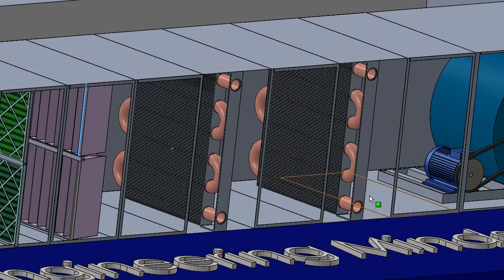It's good to have this connected so that the coldest water, and likewise the hottest water, is entering through the base of the coil and passing through. You'll get much greater efficiency out of this because it's going against the force of gravity, so it gives it a little bit extra time to give off its heat. If you configure it the other way, it's got that extra momentum of gravity, so it will pass through there and not all of it will give up all of its heat. But this is maybe an advanced step, and we don't need to worry so much about it yet.